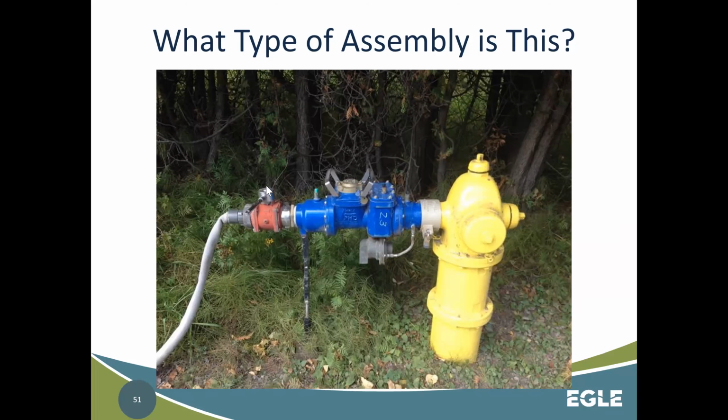You should not just be letting anyone connect to your water system to fill off a hydrant without either proper permits or proper equipment or even supervision sometimes, okay? Because Corpus Christi, Texas in 2019 alone, Corpus Christi is a resort community right along the Gulf of Mexico there, had at least 4 backflow events that were all based off hydrant filling, okay? The last one in the year that I had heard was like August of 2019 that year.